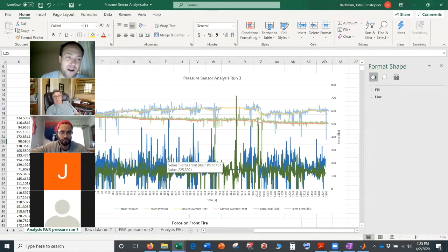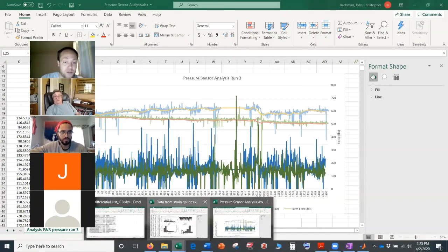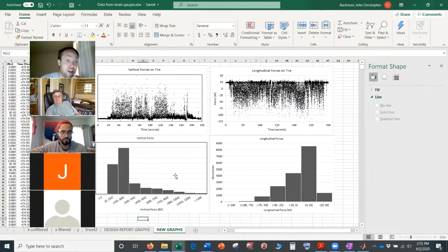So this is more info about what forces you should use, but they're pretty similar, about 5G bumps, right? So we have about 120 pounds on the front on these tires, right? So 5 times that's about 600 pounds. So both cases are saying, 600, maybe a 5G bump is not a bad case. Or we also have strain gauge data, right? So we put strain gauges on the tires. I think this over predicts